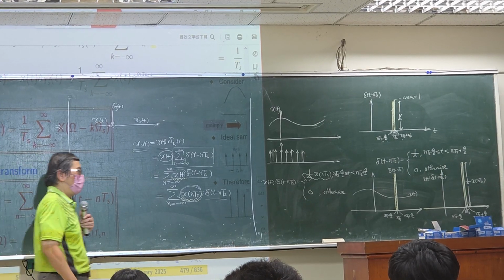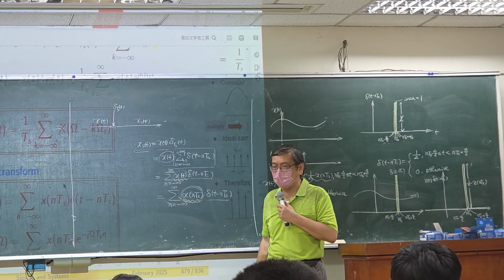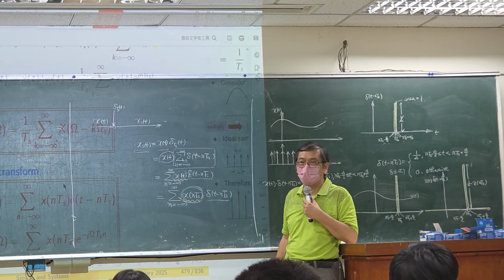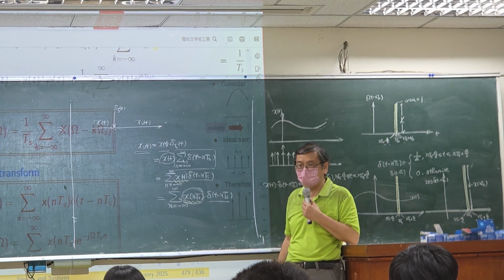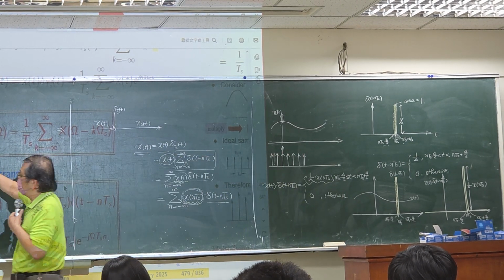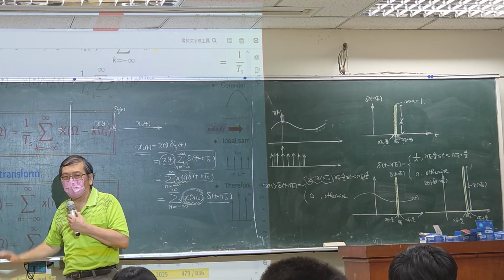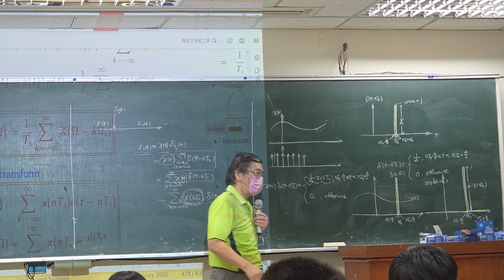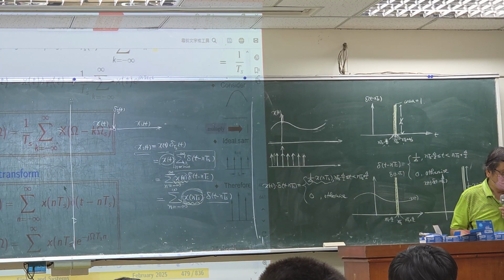You have to know how fast or how slow your sampling can be. And how do you determine your sampling rate theoretically? But practically, we may want to multiply it by 10 or smaller, up to you, depending on your application.